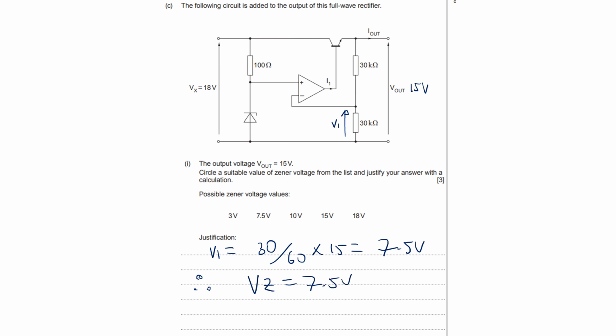And I think that's all you need to do. Let's just have a look at the equation. Yeah, that's it. There's your 3 marks. So as simple as that. Basically, the idea is these voltages have to be kept the same. Okay, that's how it works. It's really easy. Sometimes you could go a step further. You might be able to work out the current going down here, because obviously if you've got 7.5 volts there, you'll have 10.5 there, etc., etc.